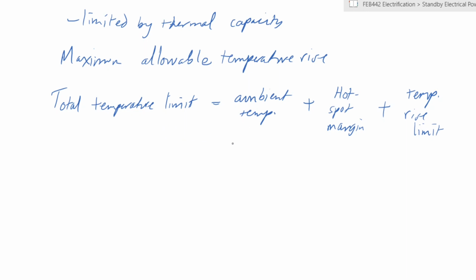The ambient temperature is defined by the temperature of air that is entering the machine. So usually that is given by about 40 degrees Celsius. So the air that is surrounding the genset as it is running, usually temperatures will be approaching that amount.